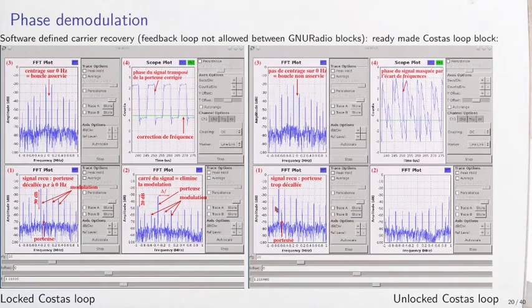Because if now we took twice the frequency offset when we square, we see that twice the frequency offset leaves the baseband. We go beyond the Nyquist frequency, and actually we get back through the positive frequency here, meaning that the control would go in the wrong direction. The QPSK loop would detect a positive frequency offset when it is actually negative, and this is because twice the frequency left the baseband.